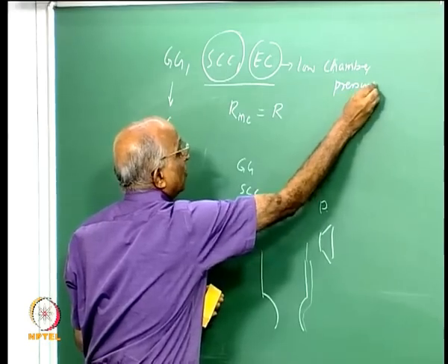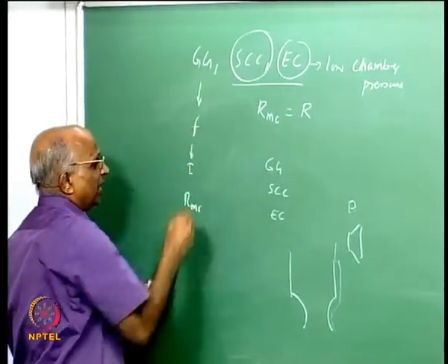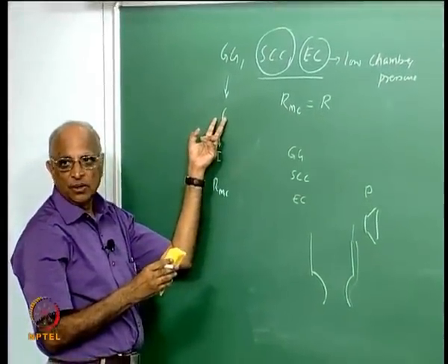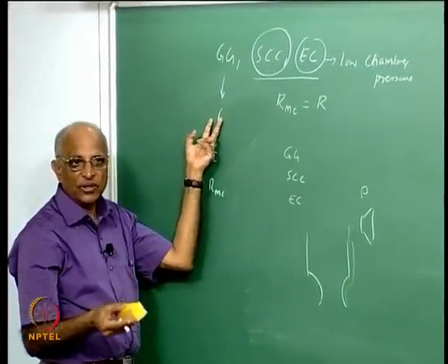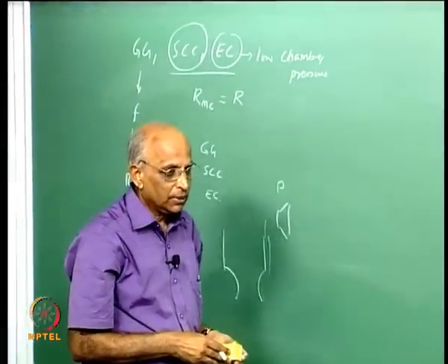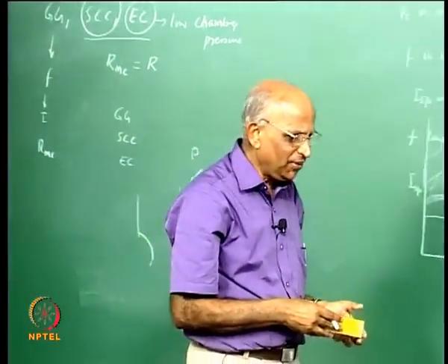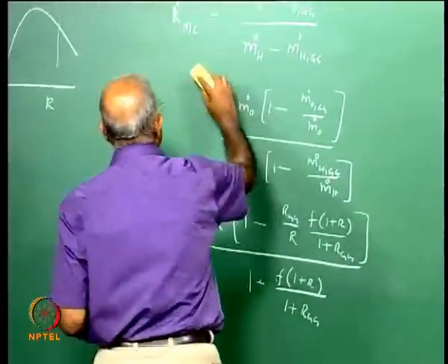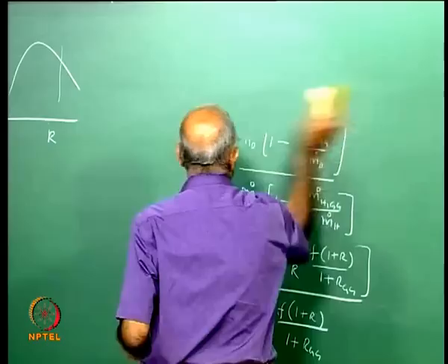But its performance will be very much higher than the gas generator cycle, because I do not use any amount of propellant in the gas generator which is not effectively expanded. I think this is all about the feed system cycles, and with this clear, let us go to the next element of our discussion, namely the thrust chamber.